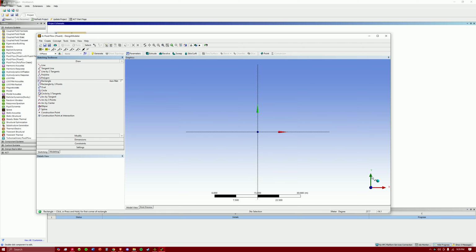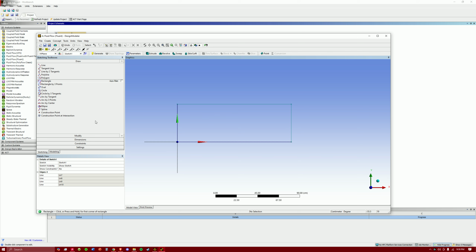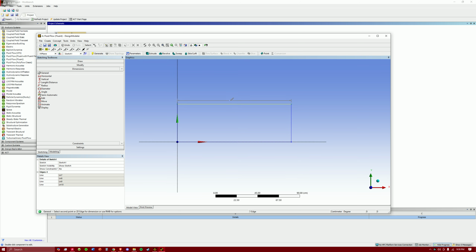You want to go to that XY axis, go to Sketch. Make sure you're in the right units up here. Makes things a little easier. In this case, since our length is 100 centimeters, I'm just going to put it into centimeters. Put that coincident, zoom out a little bit so you could just see what you're working with. Now, once you make your box, go general.